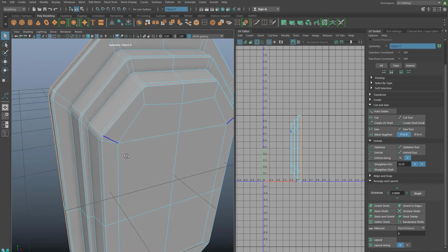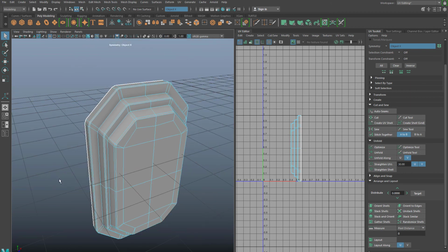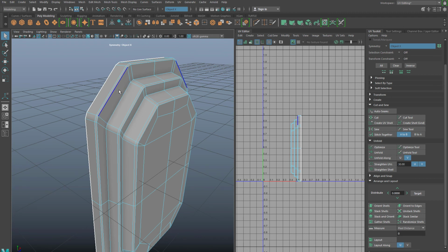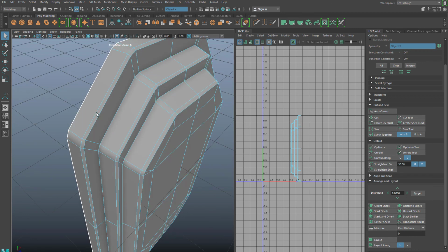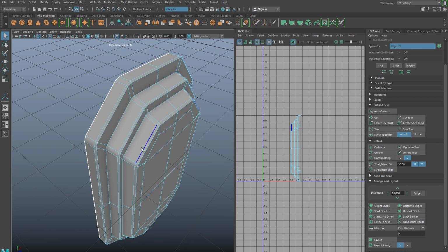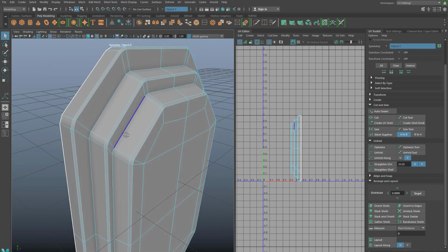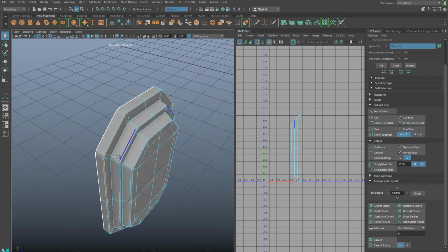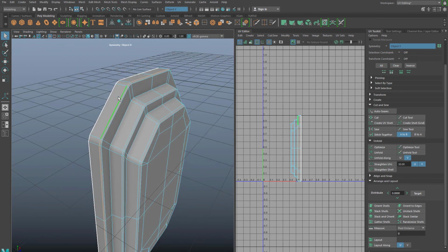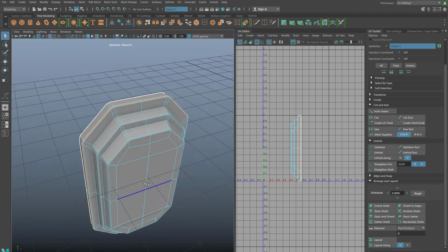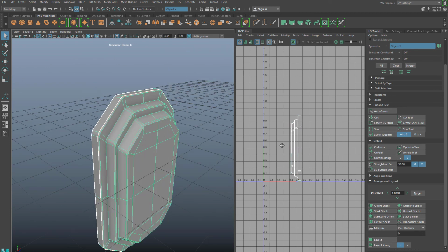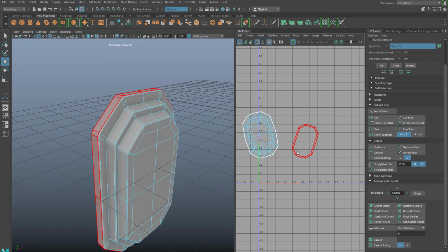And usually the way I do this is you could do the front face and unfold it, or you can take off each section individually. What I think I'm going to do is we'll just do it that way. So I'm going to take this border edge here and I'm going to cut it. That will leave the rest of this all connected. And if we go to UV shell here and hit unfold, we'll end up with two sections.